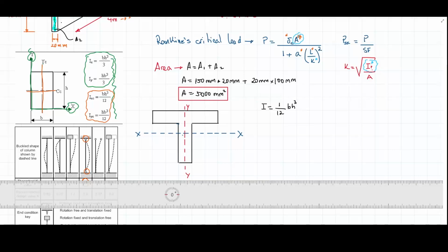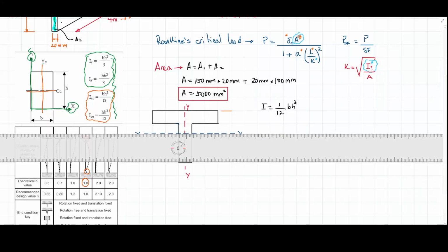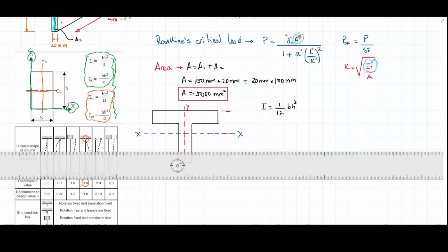To know that, I need to use the formula to calculate the centroidal axis, which is based on the individual areas of the composite section, formed by different shapes. And that formula finds the y centroidal axis, meaning this line here. So where is the distance between this and this one here? Let me put this one. So I'm going to call this one y, with the bar here, to indicate that I'm going to measure the distance of this x horizontal axis from this point here.